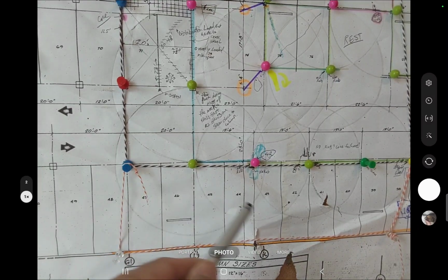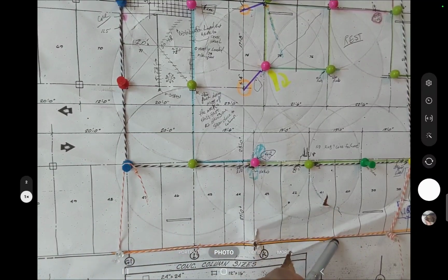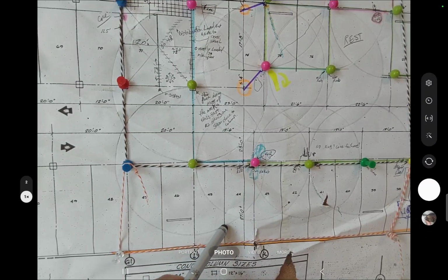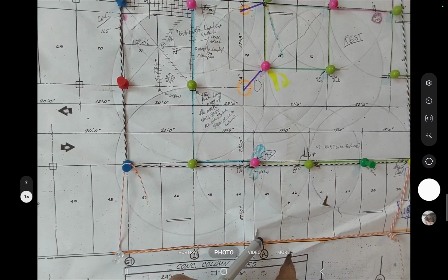Okay, let's continue. The load is distributed along this entire wall, the southern wall, but some of the slab from here is in what I call a cantilever support action, which is a critical shear zone, whether it likes it or not. Even though the reinforcement, it's because of the rigidity of it tied down to the wall below. I went over that in many videos with you. So there's a behavior, a more rigidity out to here.